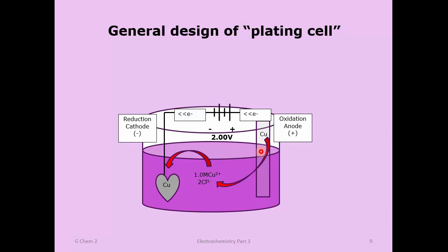If you think about a plating bath, we want to avoid the use of the salt bridge. One way you can do it is if you have a backside anode that is the material you're plating, it will continuously replenish the plating bath. So this copper will be oxidized into copper 2 plus and replenish the bath as the copper 2 plus is then continuously plated on. This is a traditional plating bath, whether it be copper or nickel or chromium, whatever you're using to plate your target.